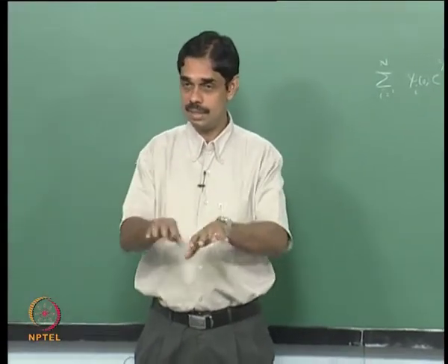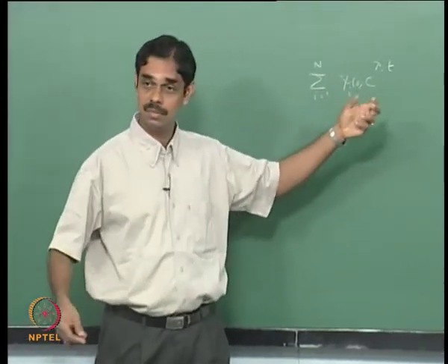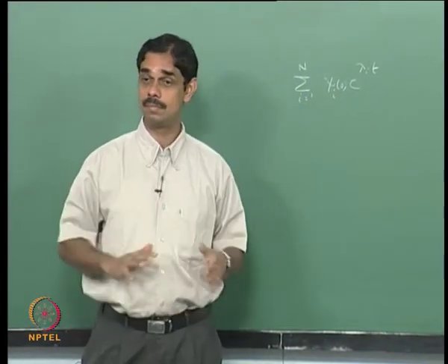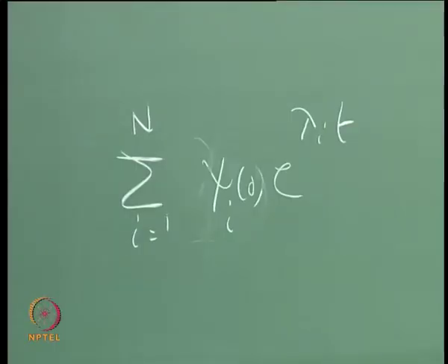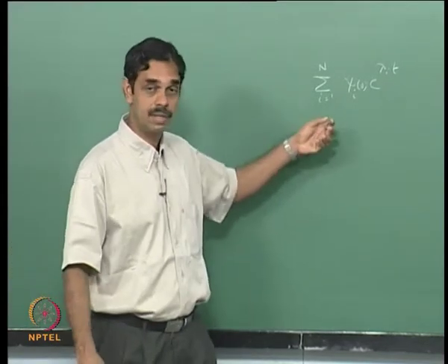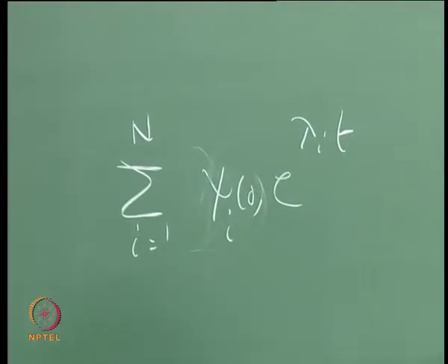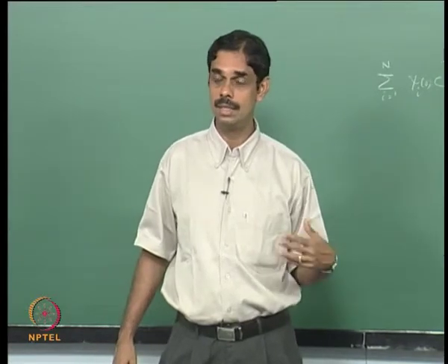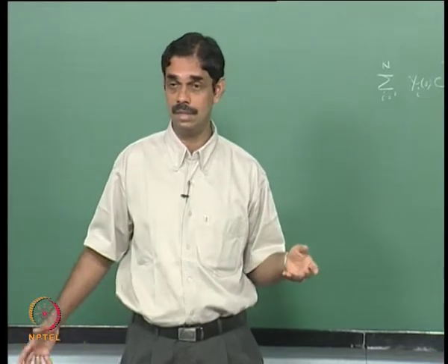You put the energy distributed into different eigenmodes, and optimal initial condition means optimal direction, in which manner you distribute the energy. A certain distribution will give the optimal initial condition. So this is the eigenvector decomposition. You can do eigenvector decomposition, or you can do an orthogonal basis, which is very convenient. That's why I used an orthogonal basis. I used the natural modes of the duct, so that's convenient actually.